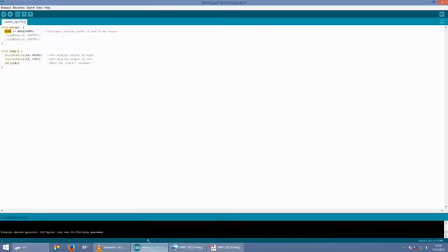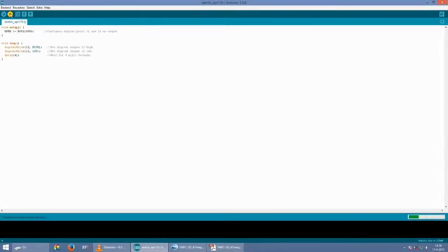The Arduino software is made user-friendly. This however comes at a cost. After compiling the code, the size is 942 bytes. When compiling the code with the pinMode commands, the size is 1078 bytes. This is caused by the extra lines that create the pinMode commands. Now let's upload the program and see what it does.